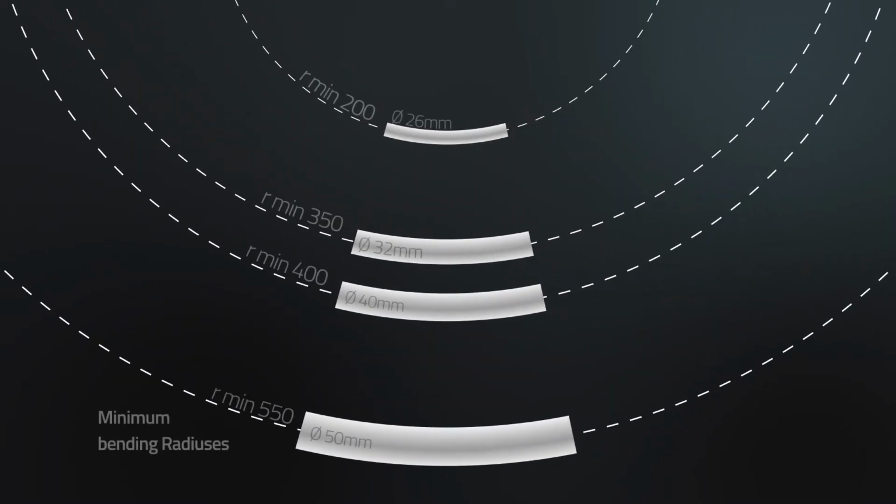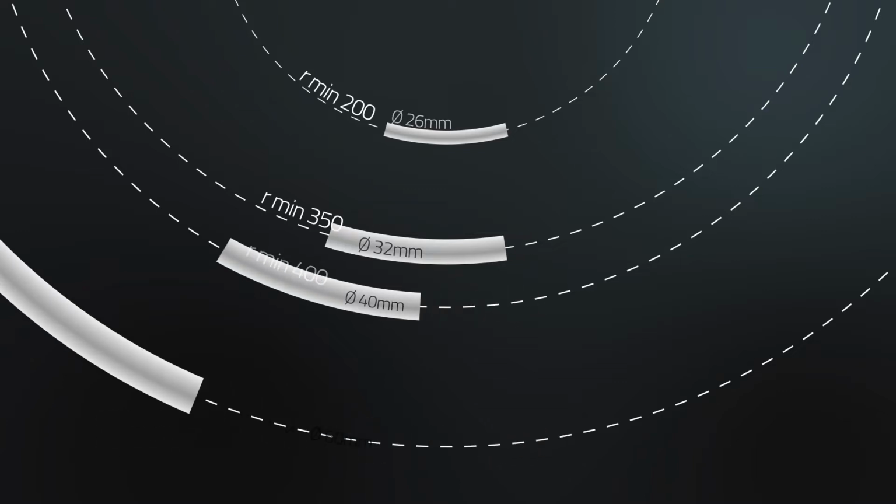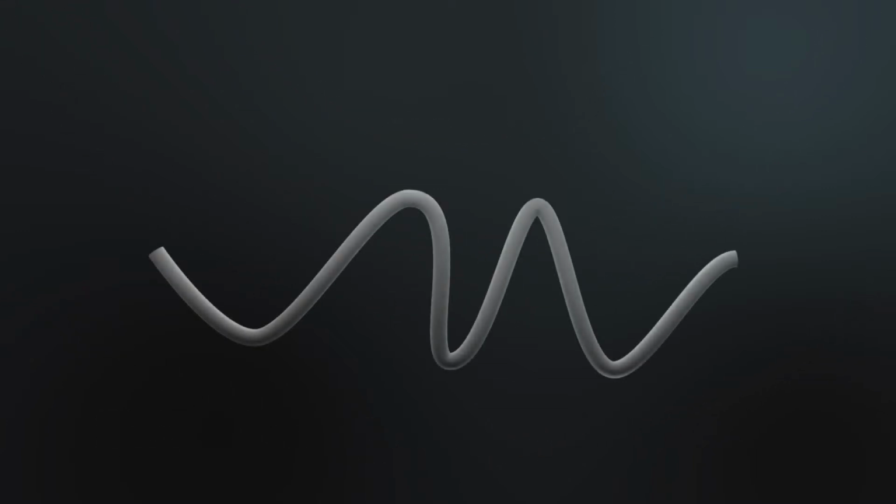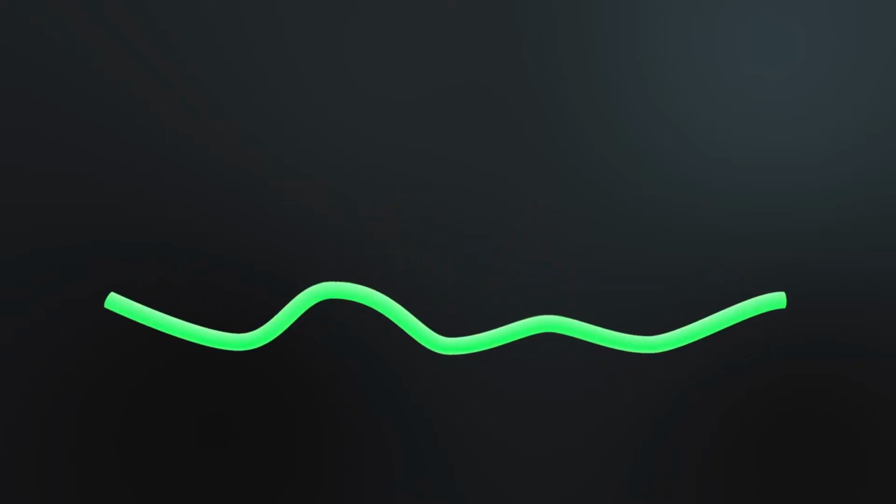Discover the minimum bending radiuses. One of the most important and basic rules of designing is maintaining the minimum bending radiuses. The larger the diameter of the luminaire, the larger bending radius it should have. Remember that very complicated structures with lamp bending radiuses often cannot be accomplished due to technological reasons. In such cases, that structure needs to be redesigned with milder bending radiuses.